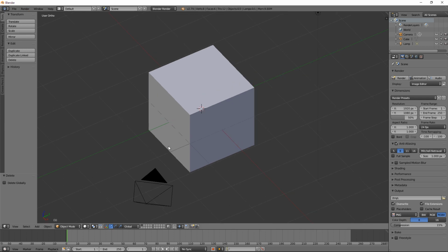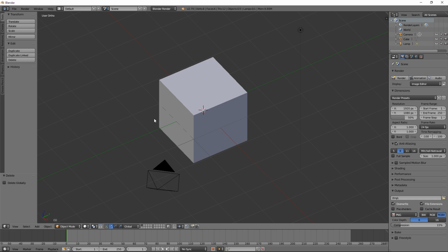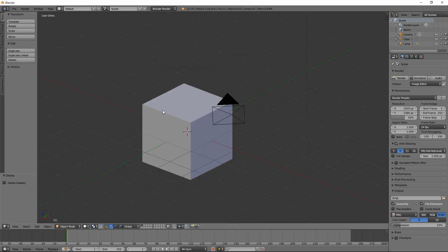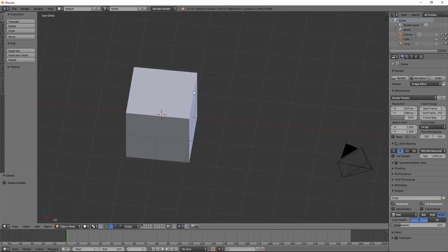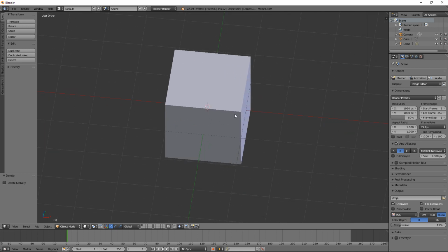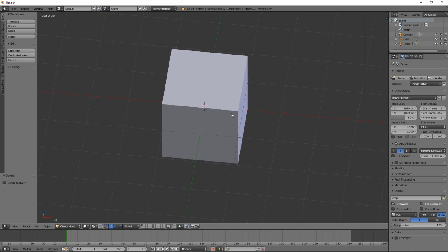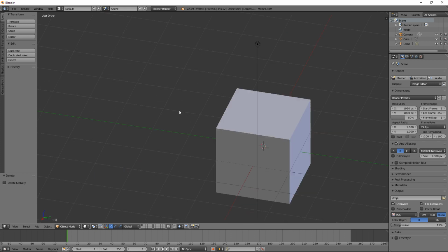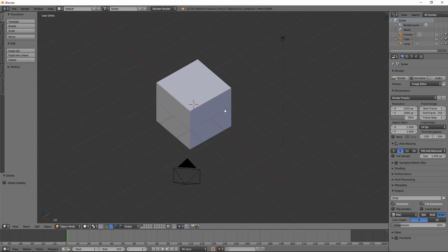Basic camera controls, basically moving around here. You're going to need a mouse with a middle scroll wheel that can be pressed down, because when you press it down, you're orbiting, okay? If you hold down Shift while you're doing that same maneuver, you're panning around, okay? In and out with the scroll wheel, pressing down on the middle mouse button and holding Shift, holding just the middle mouse button down. You get those different movements. So those are very important for being able to successfully move around.